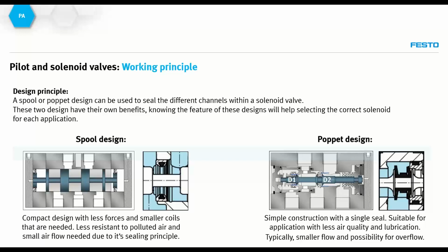This leakage flow is because of the compressed air. It's not a massive number; it's a very small percentage of the total supply pressure. But it is possible, especially with valves that are a little bit older, that they start to leak a little bit of air because the wear after thousands of cycles has worn them out a little, or particles have slipped in between the seals.